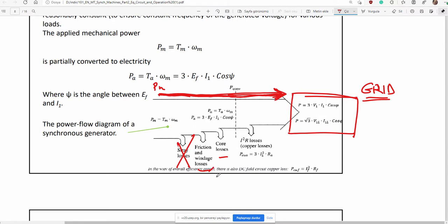Generally they are of magnetic field origin. Under heavy armature reaction, some magnetic field lines change their route and cause some additional losses. Those kinds of losses are called stray losses, but we never deal with them in undergraduate courses.